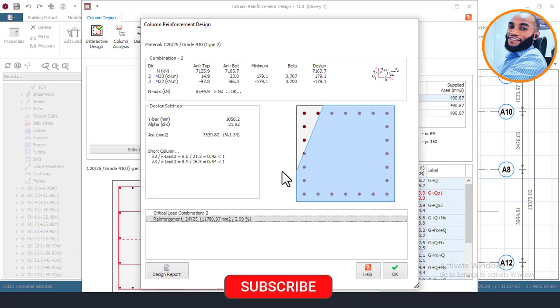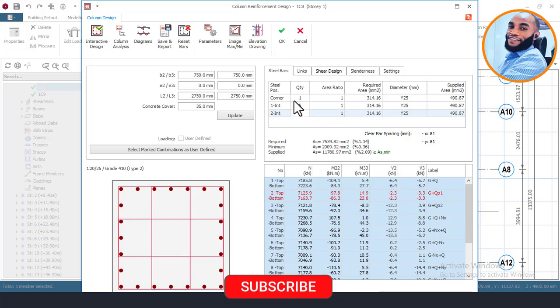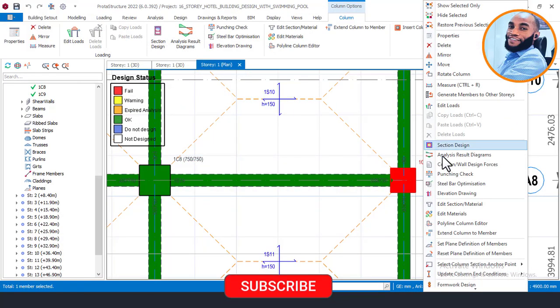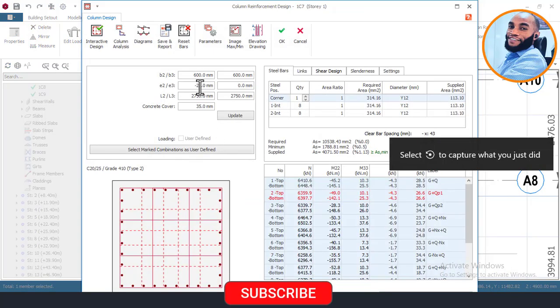So before, when we used 700, here I was showing 32 number of bars, so that was why I went to increase my column to 750, just to reduce the number of bars it's meant to use. Okay, that's fine. So I'll come here right now and click okay, and then final okay here. Okay, that's fine. So right now again, I'll come here and check, right click here, properties, come here, click here, and then reset bar first, and then design.